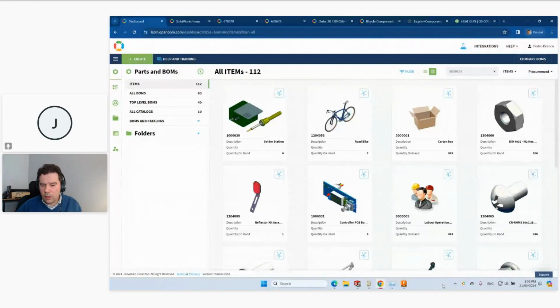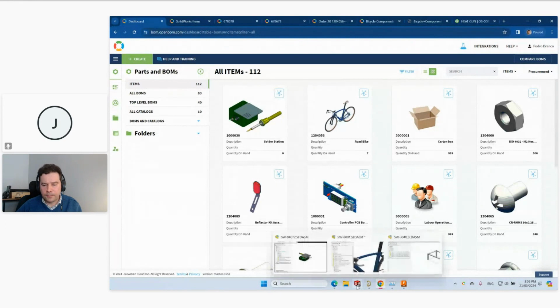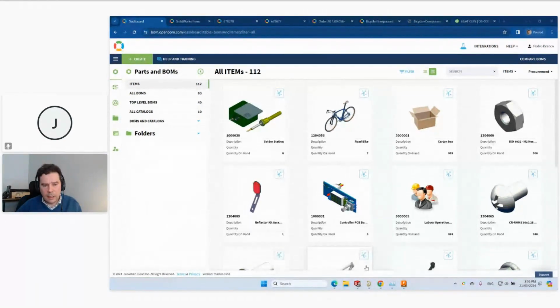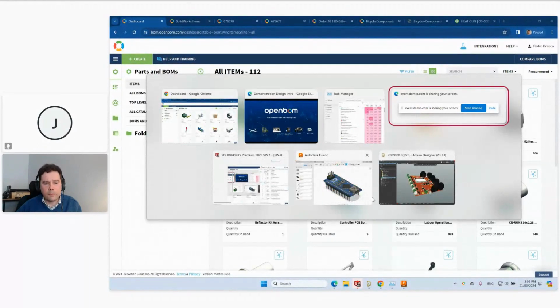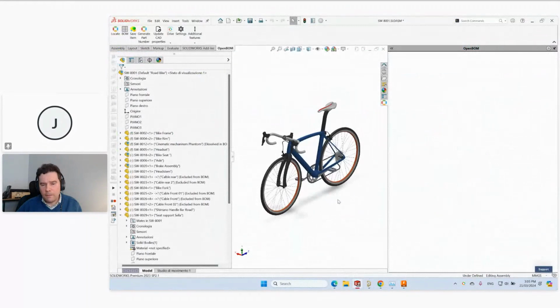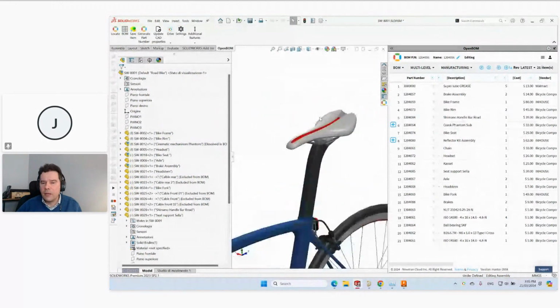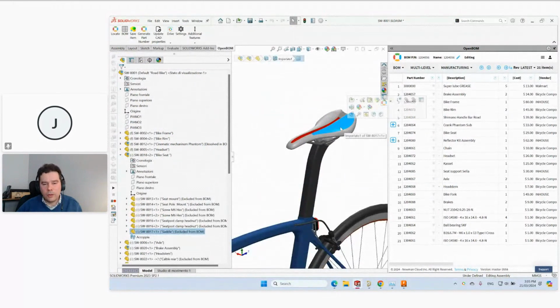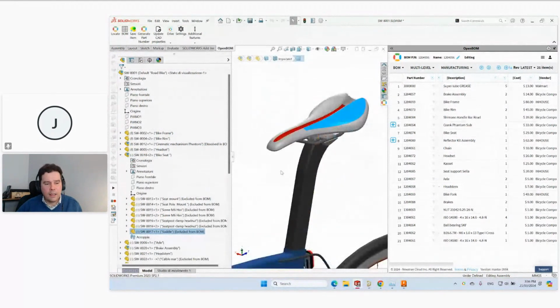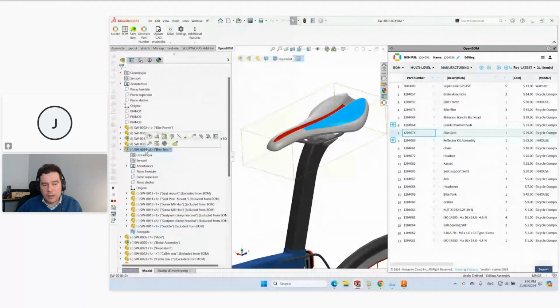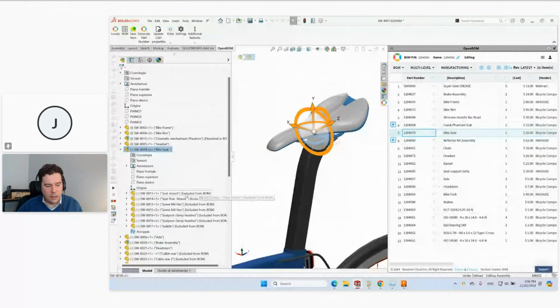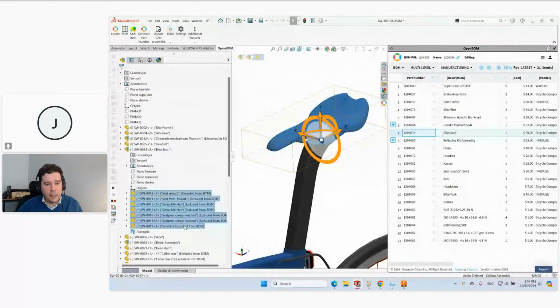So we'll start with SolidWorks. The first thing would be, for example, starting to filter the right levels that you want to send to OpenBOM. When I say right levels, it's doing things like this. If you have a purchase assembly, for example, you don't want to bring all the children. You just want to bring one item to your bill of material. This starts by using the right options in your CAD system to exclude from BOM. For example, in SolidWorks, you can just use this setting, exclude from BOM, in properties.